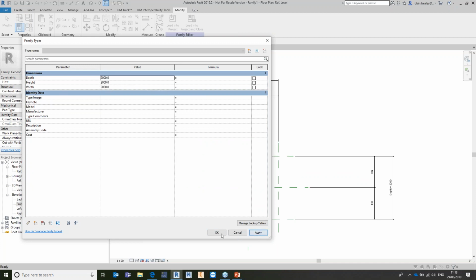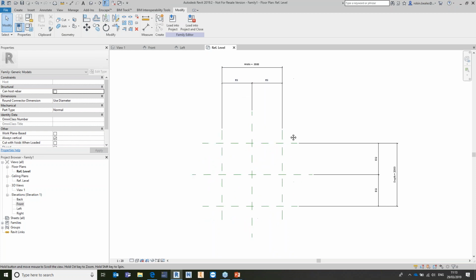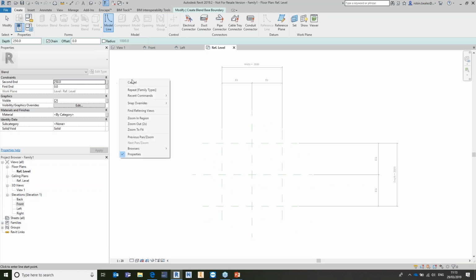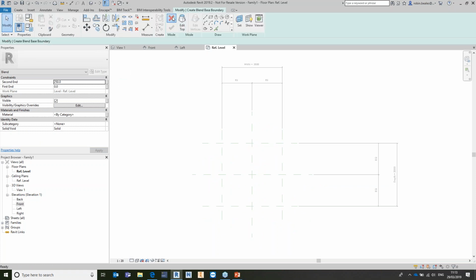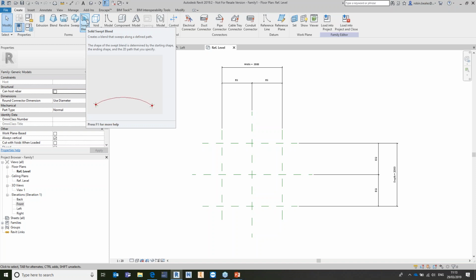So at the moment, I've not created any geometry. I've just created a skeleton. But because that skeleton flexes and works parametrically the way that I want it to, I can now very simply come in and just say, well, let's create some geometry on there. We have all of the standard functions we have in Inventor. We've got an extrude, we've got a loft, we've got a revolve, we've got a sweep, we've got a swept blend, which is basically a loft following multiple access points.